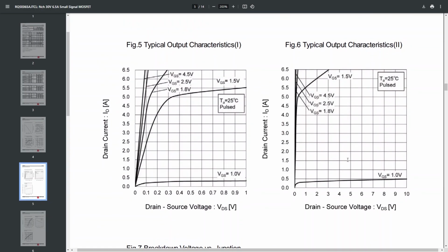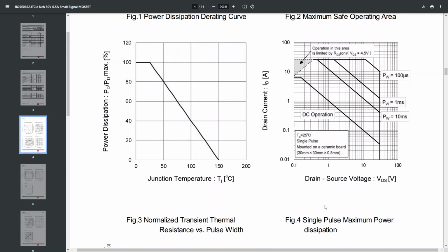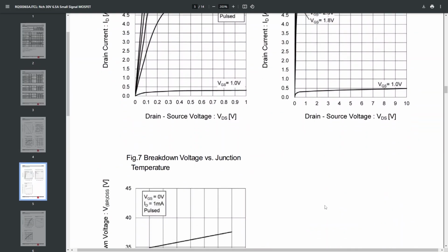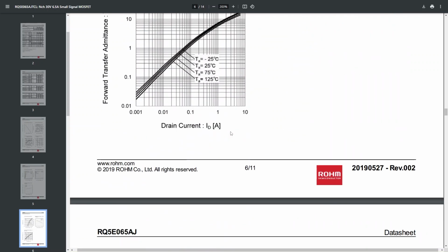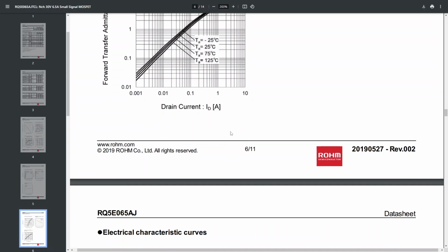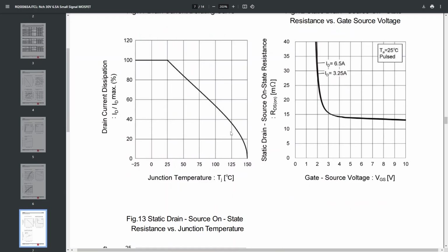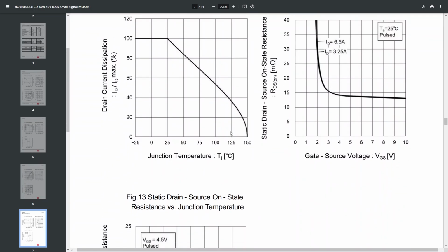And I'm just going to see if we've got, here's like so this is drain source. We want that gate voltage. So here's like the gate source voltage and the drain current. So right, what you can see is that above 1.6 is basically turning on fully. So we may have been able to go for a better logic level MOSFET or something. That may have been my limit here. This is sort of done live, so I didn't select one ahead of time.